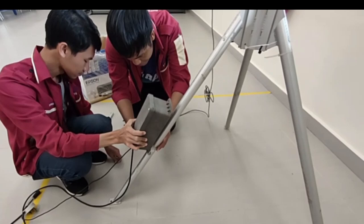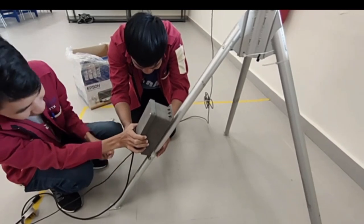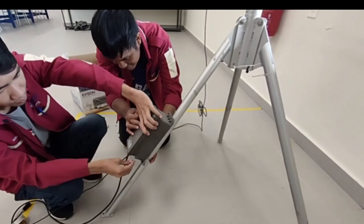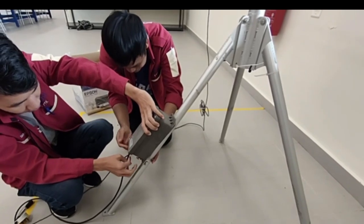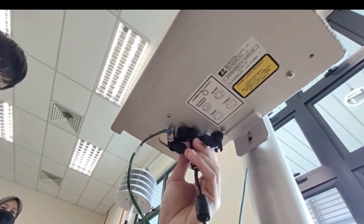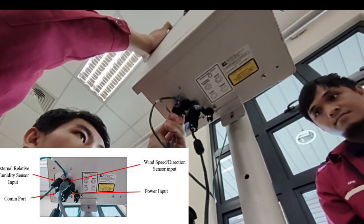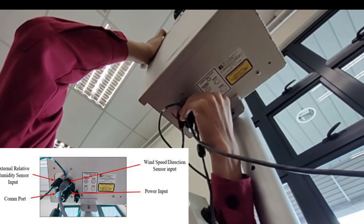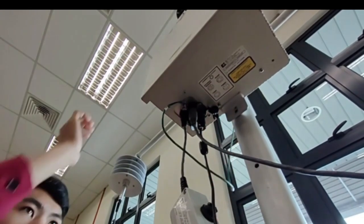The power supply was plugged into the main power connection on the bottom of the E-sampler. The power supply was attached at the bottom of the E-sampler unit and was tightened with nuts. The external input from the relative humidity sensor and the wind direction input were also plugged into the appropriate connectors on the bottom of the E-sampler. Lastly, the COM port input was connected from a personal computer for data storage.